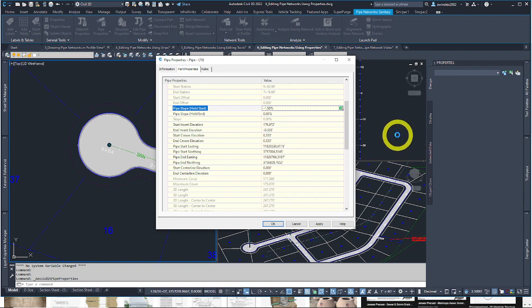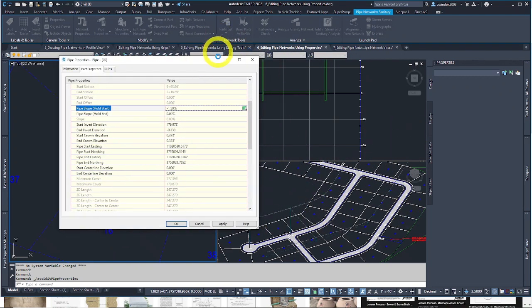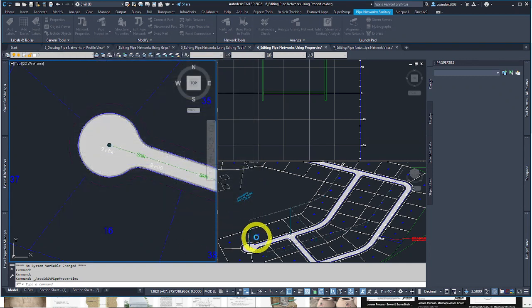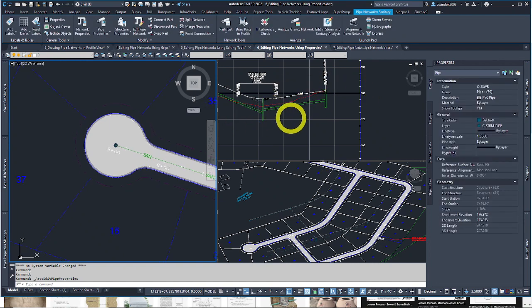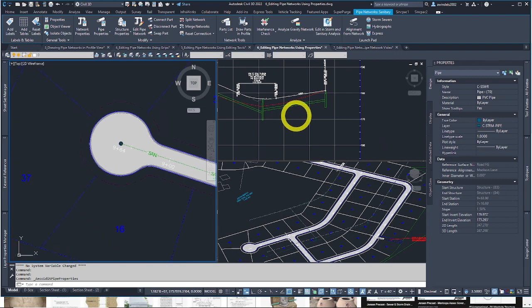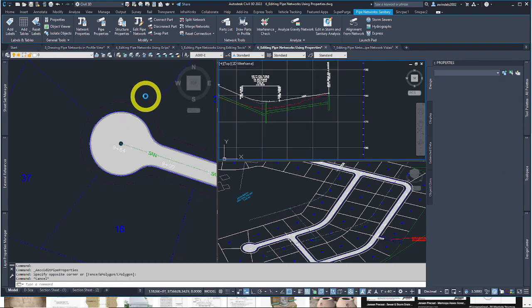And these effects are much more obvious in the 3D viewport. They get cleaned up here a lot. Let's hit OK first. These should suck down, so those big tall manholes go away. In the profile view, the manholes get to a more respectable depth in the ground to not 0. So we cleaned up a couple of those using pipe properties through Civil 3D and structure properties. Let's hit escape again to clear our selection set.